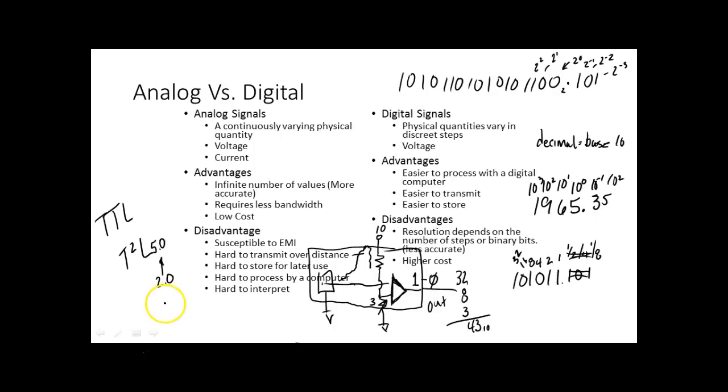Down on my low side is 800 millivolts down to, I think it's minus 700 millivolts. It would recognize this as a legal 0. So now I can live with a little bit of ground shift, right? You understand that? And we have other methods where we can live with more.